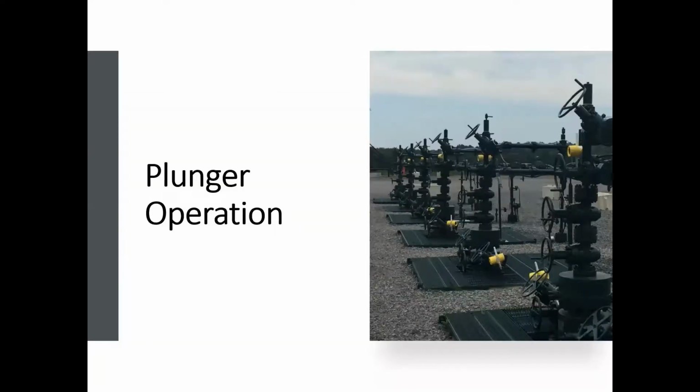So now we're going to get into plunger operations. Proper plunger lift optimization requires experience, knowledge of liquid loading and flow characteristics, and most importantly, patience. Some wells may take days to line out and others may take less than that. Just because a plunger is running does not mean the system is optimized. It takes minimal effort to make a plunger go up and down. Operators must evaluate more than just the cycles. Arrival time and speed are critical to optimizing a plunger lift system.